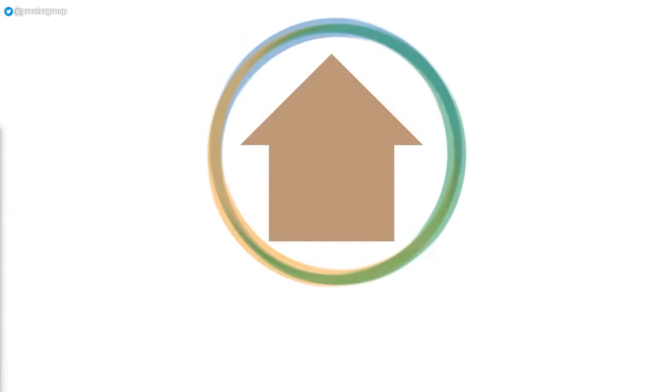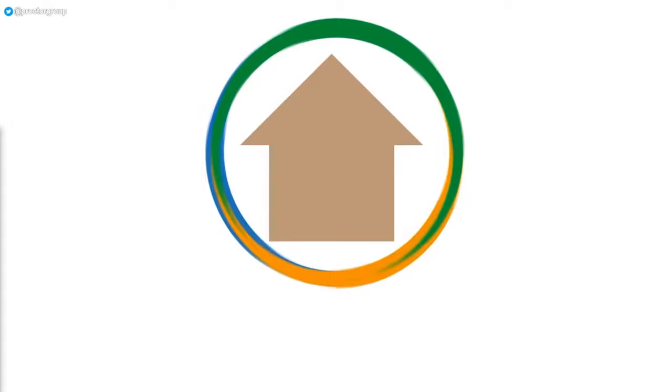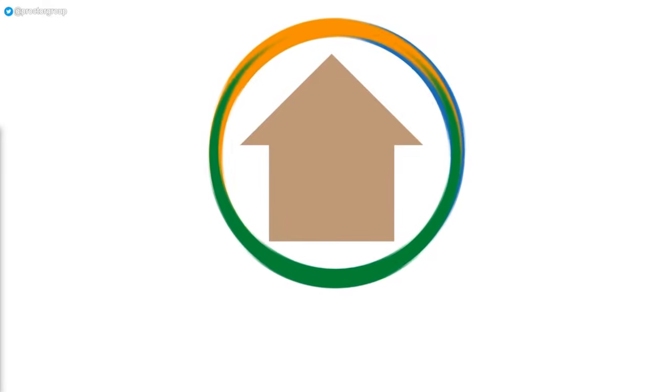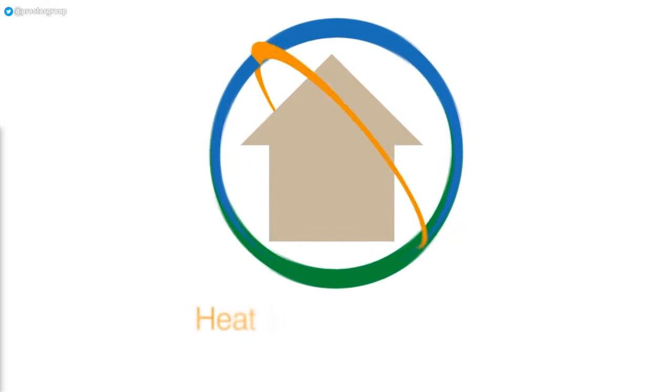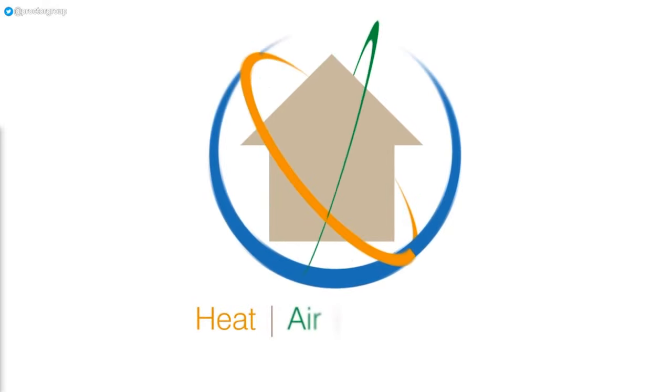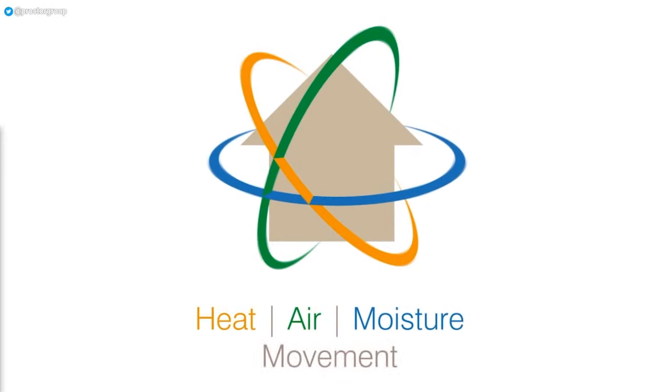Between WUFI moisture assessment and the more complex energy modelling enabled by modern BIM software, it's now possible to model the balance of heat, air and moisture accurately, and hence to design and specify with much finer tolerances. This helps ensure a cost-effective and robust building that remains fit for purpose for many years.